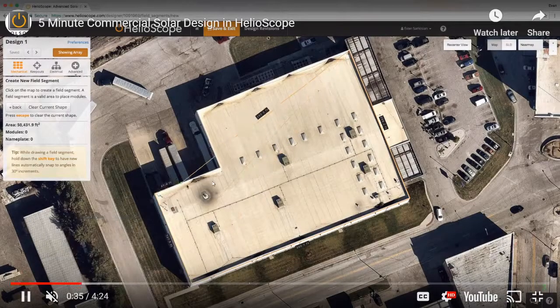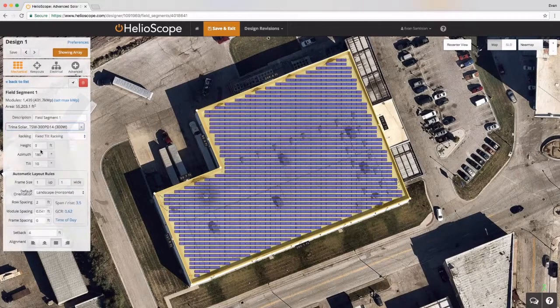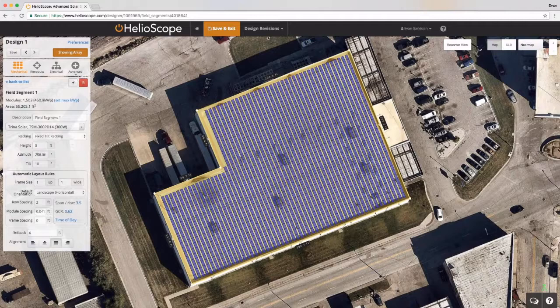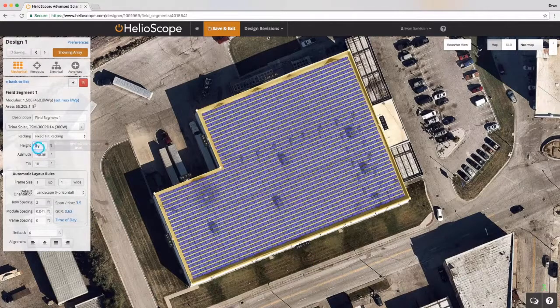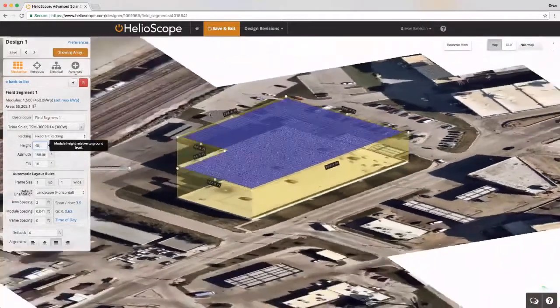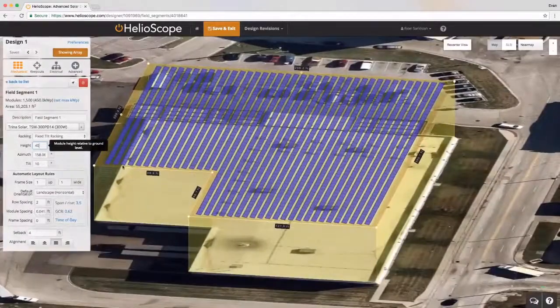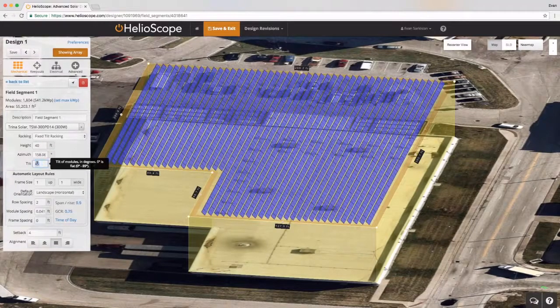And so even though they can be doing very detailed performance estimating and calculating the lengths of home run conductors and voltage drops of the home run conductors, they're kind of stopping before they become full-fledged construction documents. Sometimes that can get a little annoying when you're doing commercial projects and the developer has only done a HelioScope design and they just use that to go out to bid.